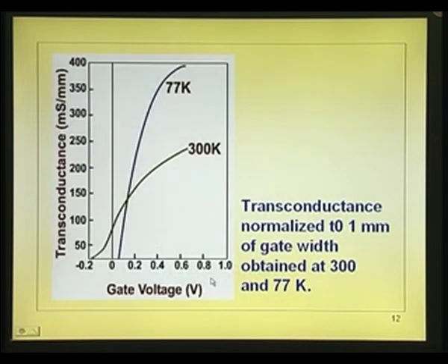One thing that one should note here is, as you go up here to larger and larger voltage, the transconductance increases, okay, because VGS minus VOFF is increasing, number of electrons are increasing, but then afterwards it does not increase that steeply, it gradually tapers off. It tapers off because the mobility of the electrons tends to fall down.